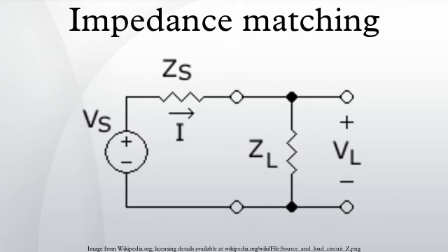If an explosive charge is placed on a target, the sudden release of energy causes compression waves to propagate through the target radially from the point charge contact. When the compression waves reach areas of high acoustic impedance mismatch, tension waves reflect back and create spalling. The greater the mismatch, the greater the effect of cracking and spalling will be. A charge initiated against a wall with air behind it will do more damage to the wall than a charge initiated against a wall with soil behind it.